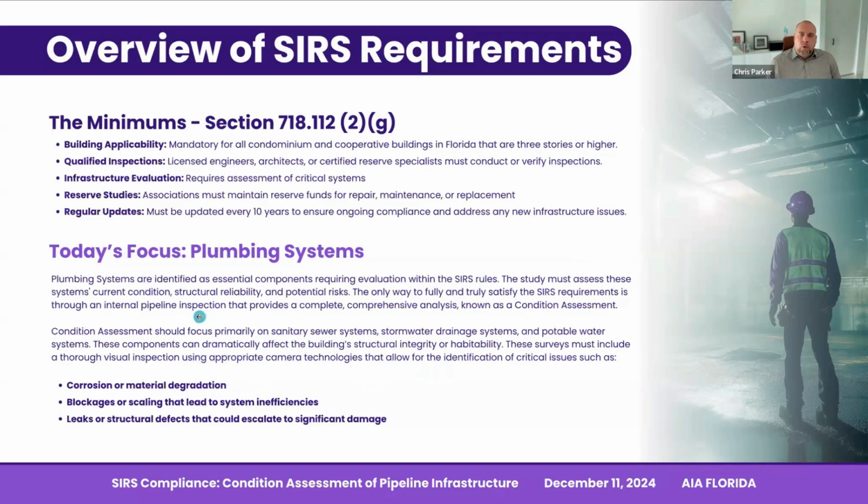We have a couple questions coming in, so I'm going to address those before I move to the next slide here. So the first question is, what is the estimated longevity of a sanitary sewer system in a Florida high-rise residence? So that is going to vary whether you're in a coastal community or an inland community, the age, but generally speaking, cast iron starts to degrade in about 30 to 40 years.